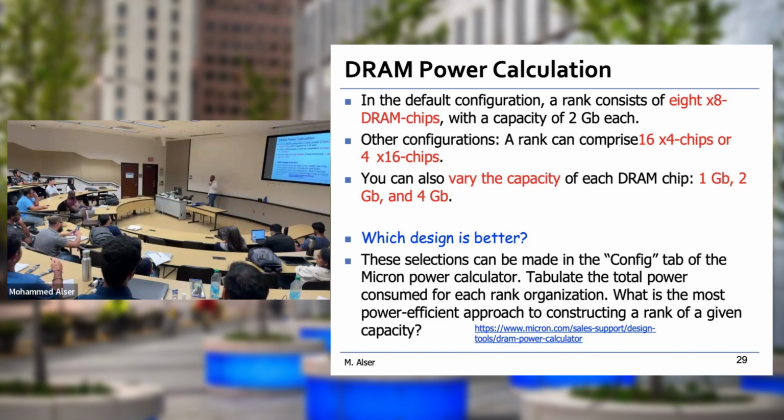Unless I have two memory controllers or two channels, right? You remember the mesh topology? Then I can alternate between the DIMMs. I get this one, then this one, or both of them at the same time if the topology allows for that. So if you have two memory controllers, two channels, it solves the problem. It doesn't matter now whether you double or have two of them, it's the same effect. You can access both of them in parallel, and maybe it will be much better than even doubling the size. Do you understand the question? Do you understand the answer? This is really important.